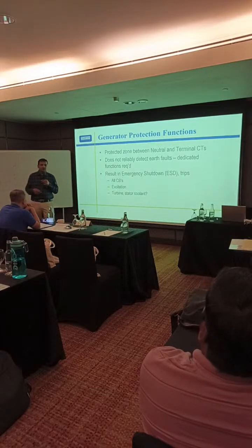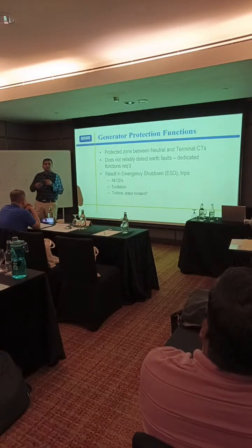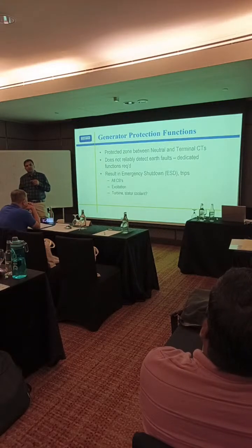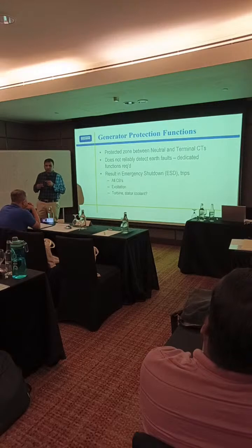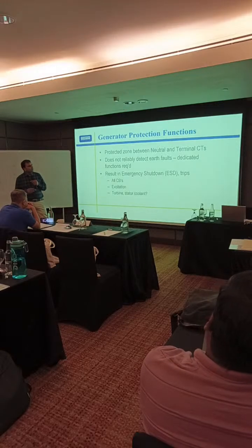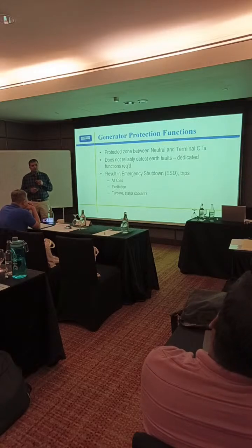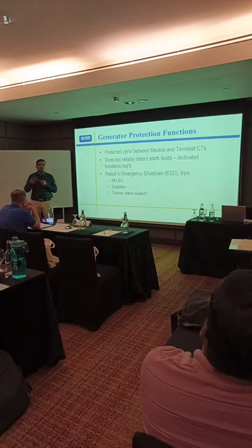So that is why we have additional protections, stator protection for 95% and 0 to 5%. Additional protections are especially for earth fault conditions. So these differentials work very well for phase-to-phase faults, but for earth faults, we have multiple protections in the generator.